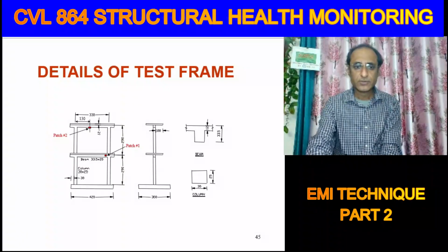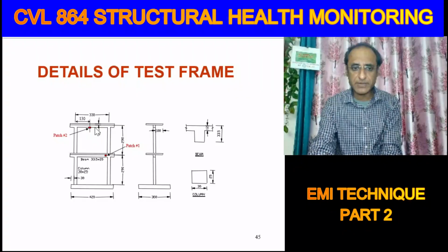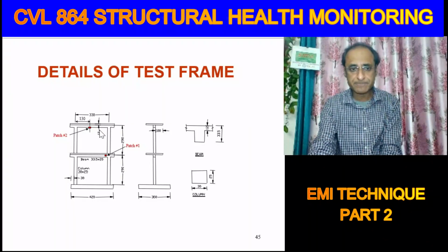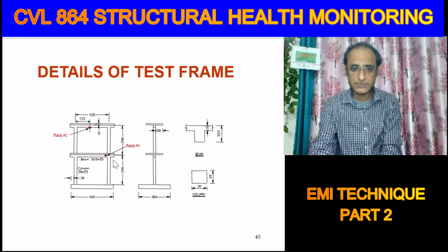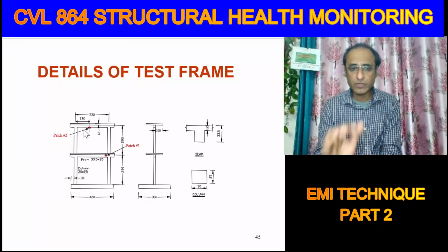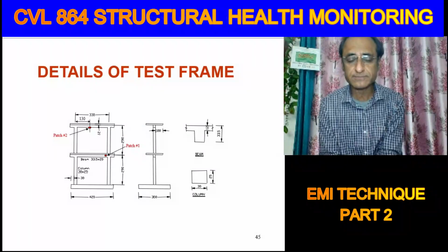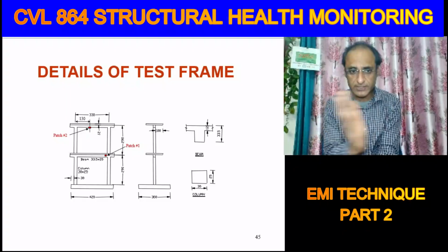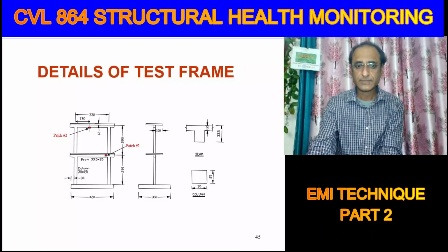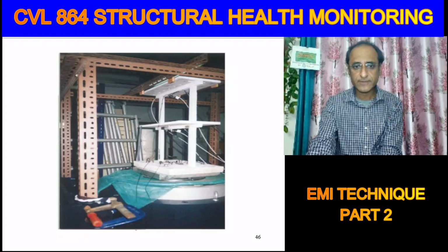So here I was also a participant, and I had installed 2 sensors. You could see here one piezo patch near the mid span of the second floor beam and one patch near the joint here in the first floor beam. I hope you can see both these patches. Now this patch number 2 was not positioned exactly at the midpoint, the reason being that there was some other instrumentation near the midpoint, so it was a little bit off the midpoint.